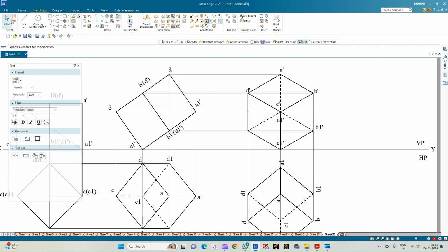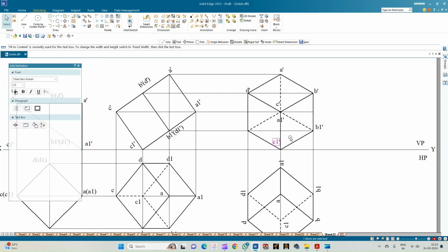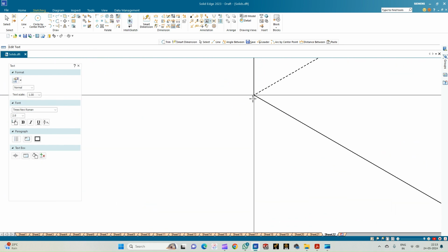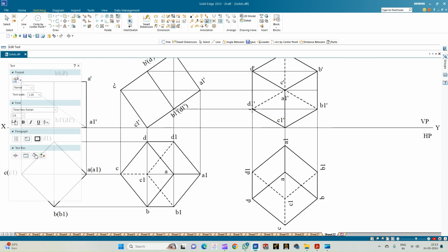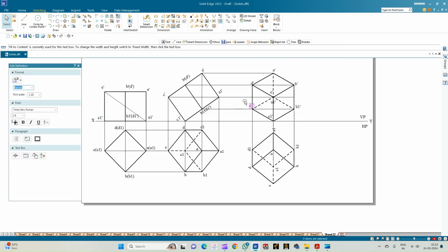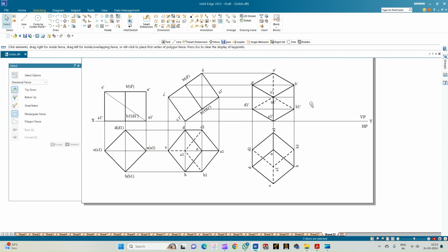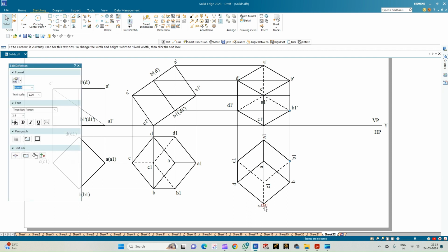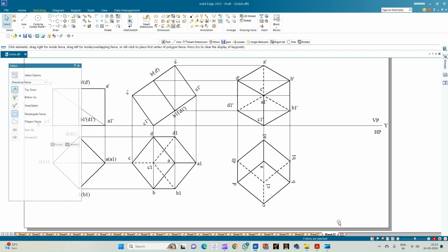So you can just see that all the points, that is A dash, A1 dash, C1 dash, and C dash, will all lie on the same projection line. And then we'll complete it with the corner D1 dash. So now you can just see that the solid diagonal that we have considered in the first position, that is C dash to A1 dash, C dash to A1 dash is perpendicular in the vertical plane. So with this, we complete the solution for the given problem statement.